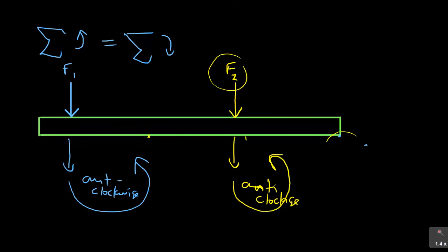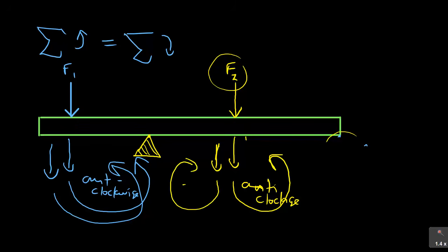if you remove that and change my pivot to somewhere here, you saw that a different scenario occurs, whereby the first force, F1, will have the same anti-clockwise rotation. But if you look now at F2, F2 has changed. In this case, F2 is still going downwards, but it is making this beam rotate in a clockwise rotation. So you need to be careful and aware where the beam is, and what the effect of that force is whenever that beam is going to be turning.